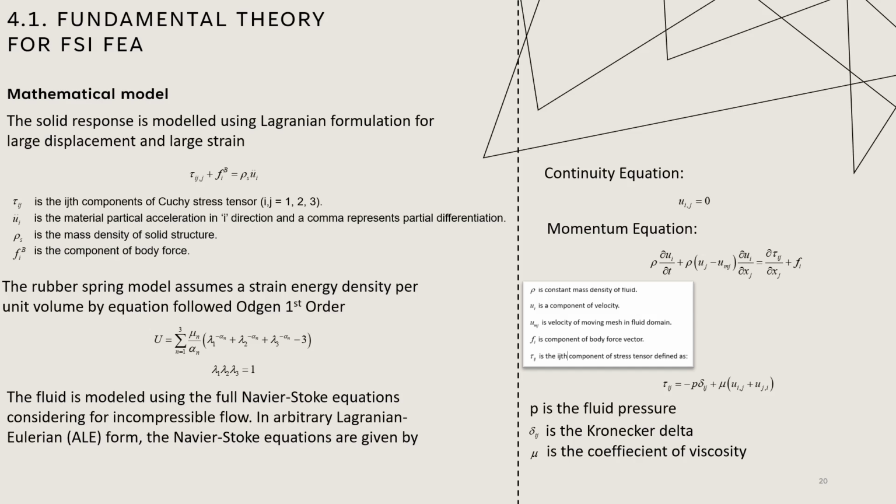Secondly, we're gonna discuss the rubber spring and the rubber bellow in the hydraulic engine mount, because it is a rubber, so it is a hyperelastic material, and you have to use a hyperelastic model to represent that material property. So in order to do that, you have some types of models that you can use, like Mooney-Rivlin, you have Ogden, depending on what order you're gonna use.